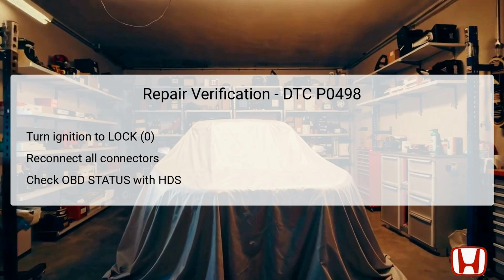Begin by turning the ignition switch to the lock 0 position, which ensures all systems are turned off. Reconnect all previously disconnected connectors to restore the circuit integrity completely. Then, turn the ignition switch to the on 2 position to prepare for diagnostics. It is advisable to reset the ECM (engine control module) utilizing the HDS to ensure it adapts to any new changes made. Finally, do an idle learn procedure to recalibrate the engine settings, followed by monitoring the OBD status in the DTCs menu with the HDS.